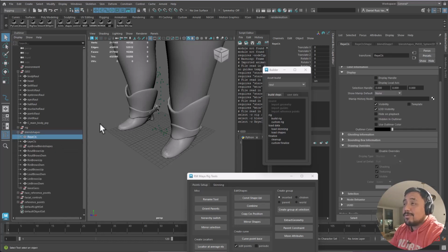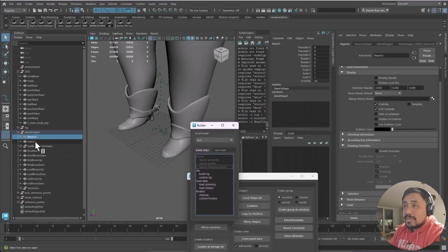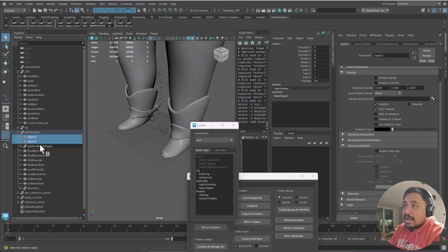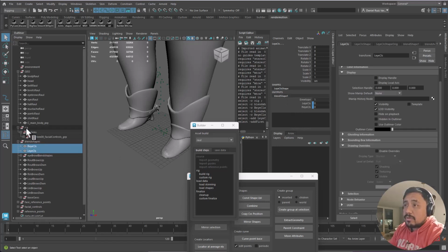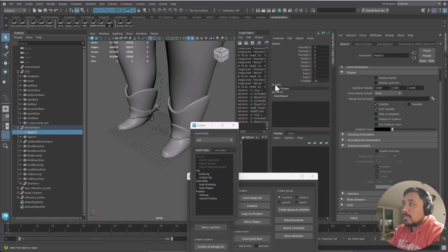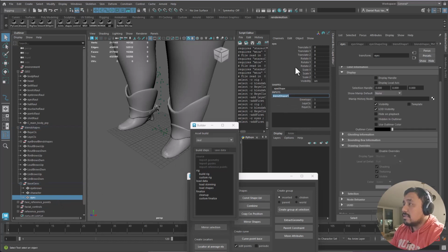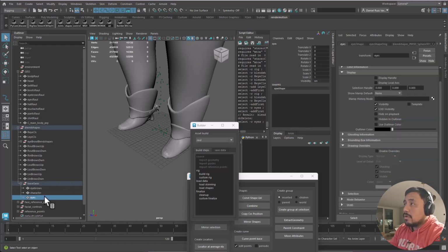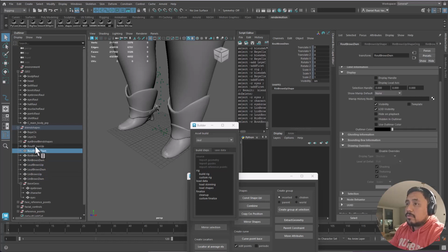I think it's going to be the blend shapes. And the reason is because when I selected the blend shapes and I saved them, I didn't realize that they have a blend shape applied that is linked to the control. So let's delete this. Let's see. Blend shape, outputs blend shape. There's still a blend shape node applied to the eyes, maybe base geos eyes. Yes, it's here. Let me delete it. We don't need it applied or anything. We need clean geo. It is clean geo. Okay, there you go. So everything is clean. It looks like it's clean.